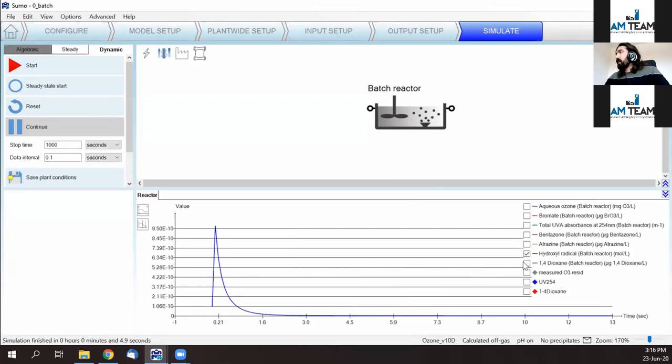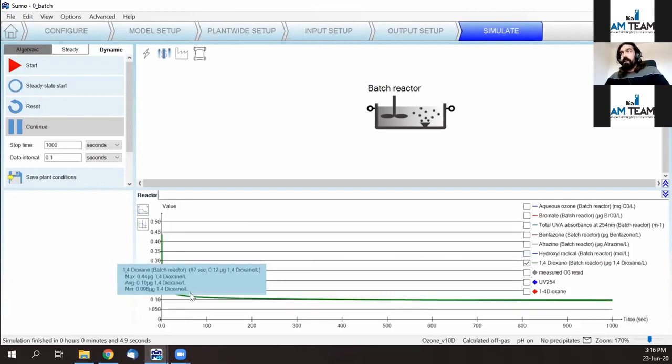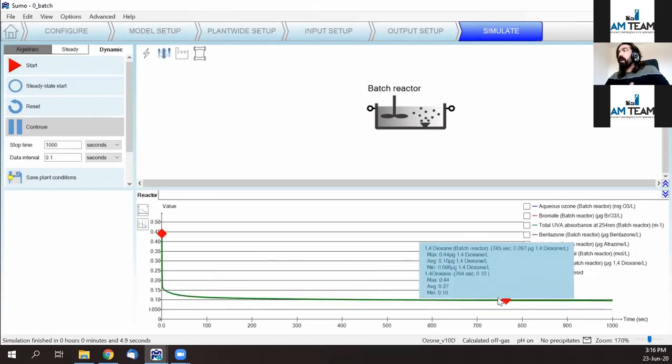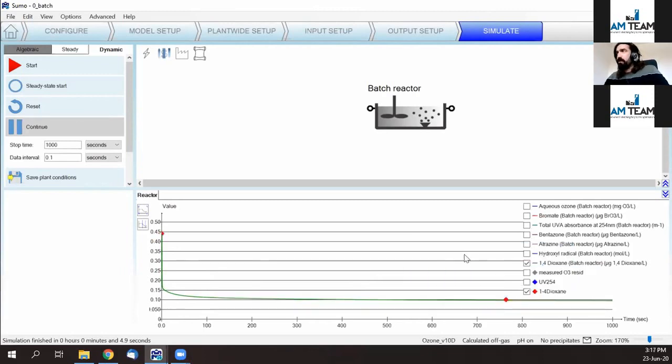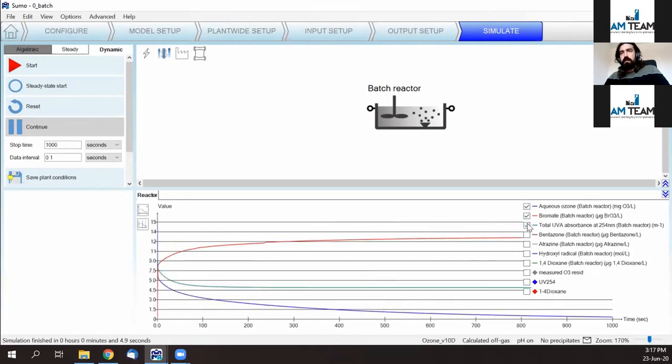of the substrate. Now, if you know your ozone residual and your hydroxyl radical concentration, then you can also know how much micropollutants are present there, because their reaction rates are known, and you can nicely measure effluent concentrations of this experiment. But nonetheless, ultimately, you can include in this complex picture of reactions also the reactions due to bromate formation.